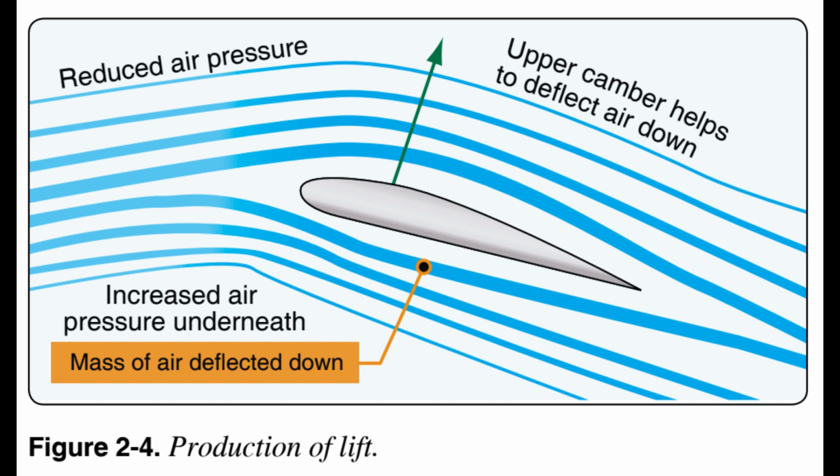However, the details of how the relative movement of air and airfoil interact to produce the turning action that generates lift are complex. In any case causing lift, an angled flat plate, revolving cylinder, airfoil, etc., the flow meeting the leading edge of the object is forced to split over and under the object. The sudden change in direction over the object causes an area of low pressure to form behind the leading edge on the upper surface of the object. In turn, due to this pressure gradient and the viscosity of the fluid, the flow over the object is accelerated down along the upper surface of the object.